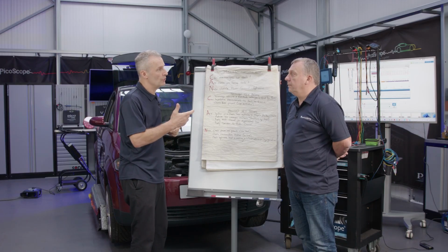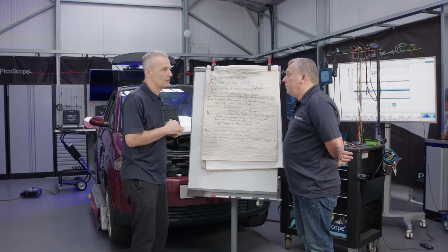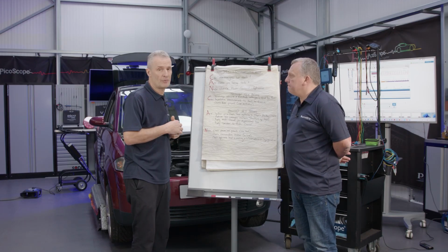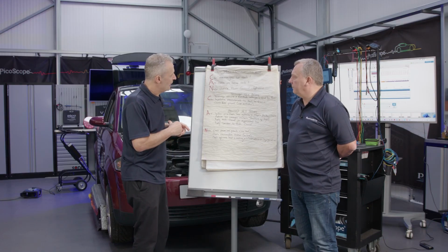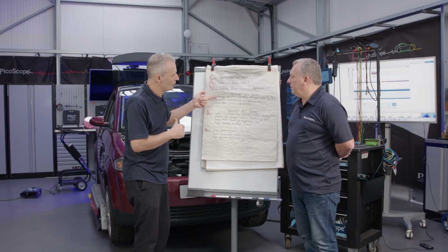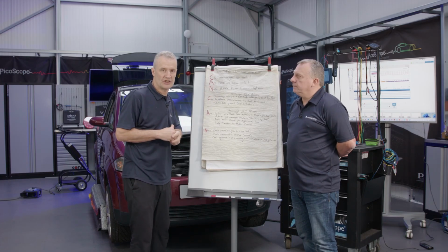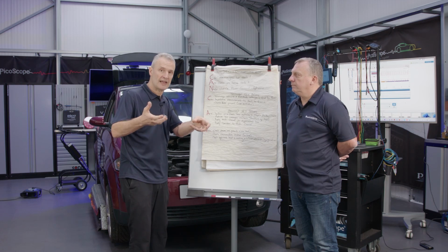What was interesting on the short to ground we had here, it turned out not to be relevant. This was what we thought was a short. I can't remember what it was. Was it over 260 odd? Oh, 270 ohms. Yeah. So that was proven. That must have been leakage through transceivers. Yeah. This has caught, not to say caught us out, but it was a bit of a revelation. The fact that we got voltage, a differential across the two terminals of the batteries leads when they were taken off the battery.